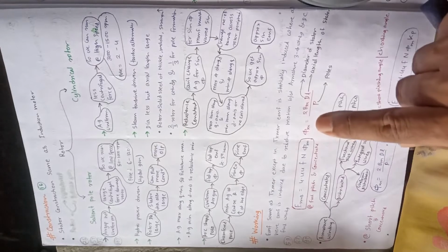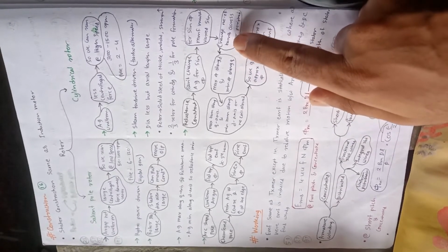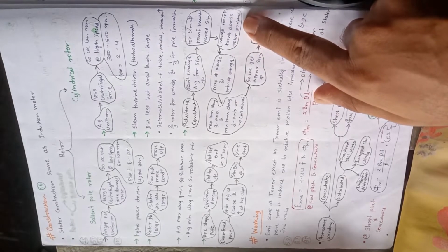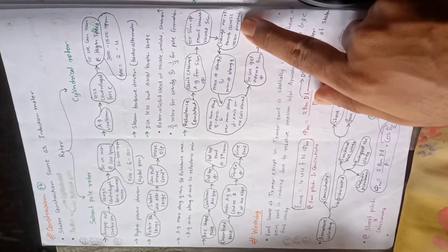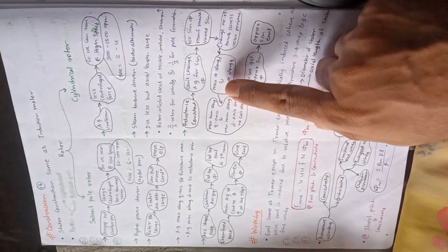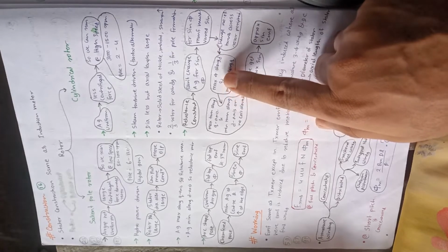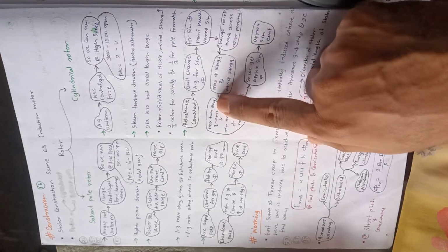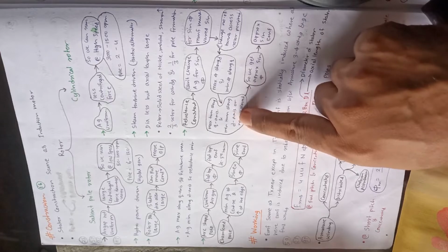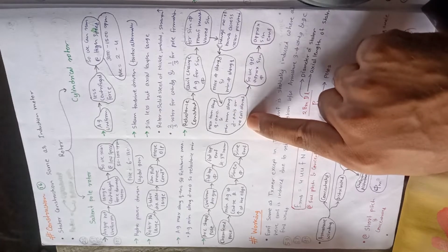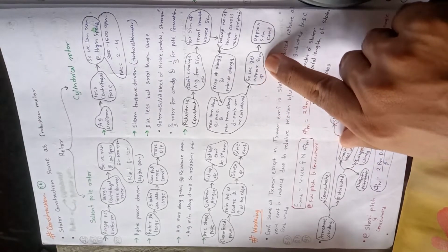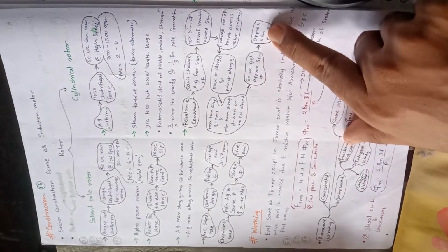To do so, we have to change the number of turns across the rotor periphery. Where we have to change the number of turns, now we will decide that. Actually we want maximum flux along the D axis and minimum flux along the Q axis. To get that condition, we have to put maximum turns along the Q axis and minimum turns along the D axis. Then we get approximately sinusoidal flux, and hence we get sinusoidal EMF.